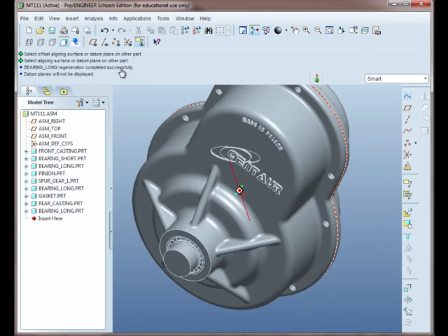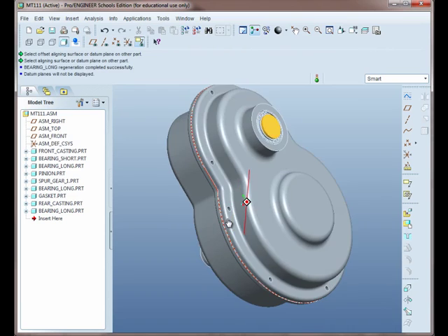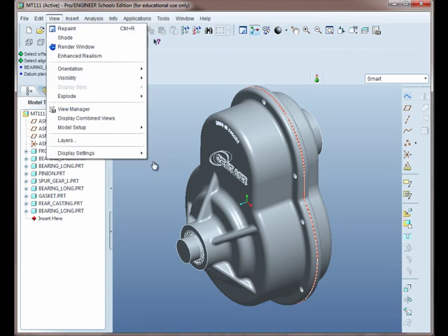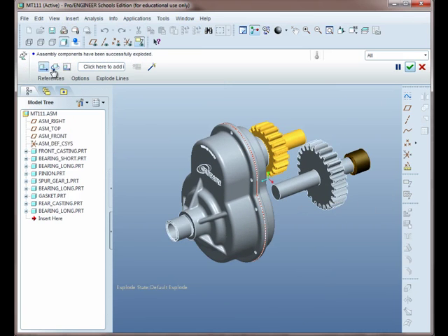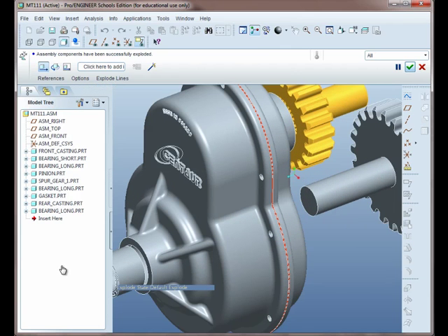Alright. The last stage here is to bring it into a drawing, create the bill of materials, and explode it. So actually we need to explode it next because we do that here in the assembly. So to explode this, we need to go to View, Explode, and just hit Explode View, or actually Edit Position. Now you'll see it will have some prearranged explosion going on there. That's okay. We need to add to it. So what we need to do here is we just need to select a reference like an axis or an edge.